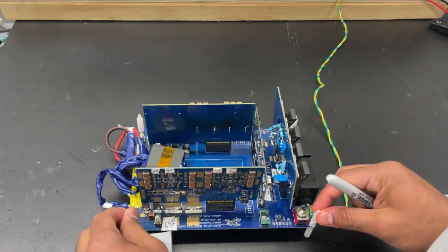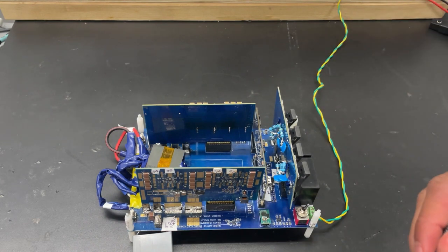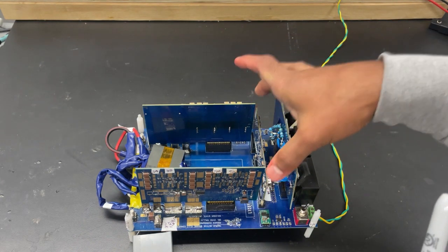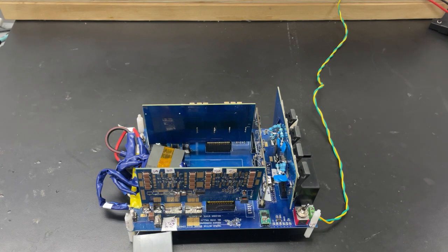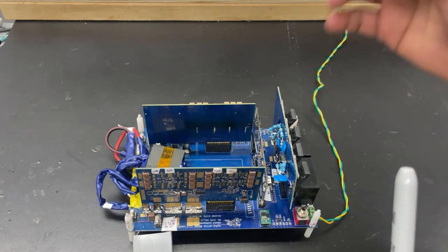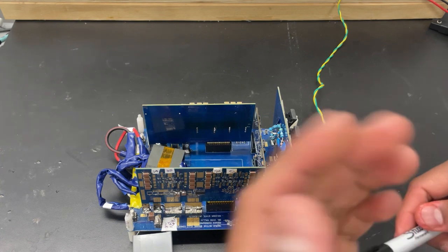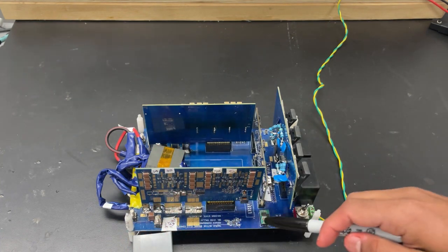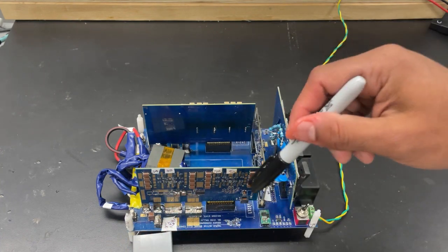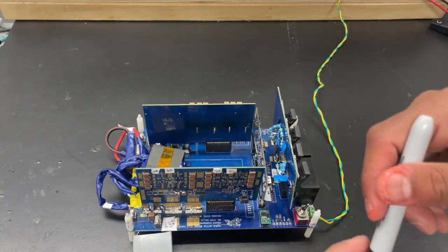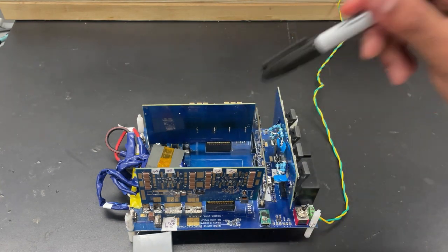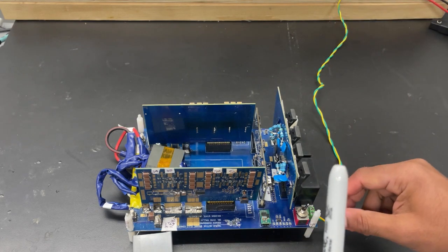Finally, coming down to the controller, we are using this particular daughter board, which houses the TMS320F28379D microcontroller, which is being used to send the gating pulses to each of the active bridges. We also have the auxiliary circuit. At the input we provide 15 volts, which is then converted to 5 volts using this particular DC-DC converter, and that 5 volts is then used to provide power to the gate driving circuitry on the 3 active bridges, as well as power to the microcontroller.